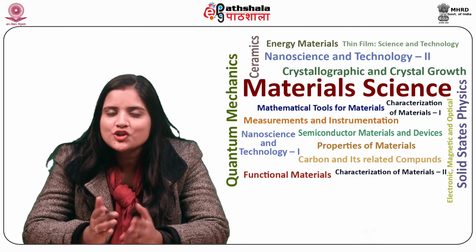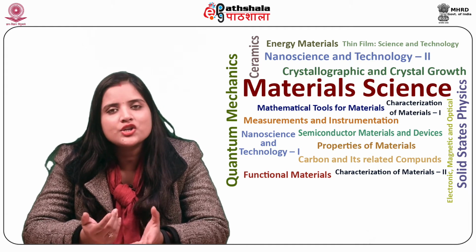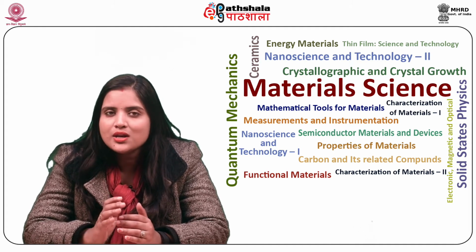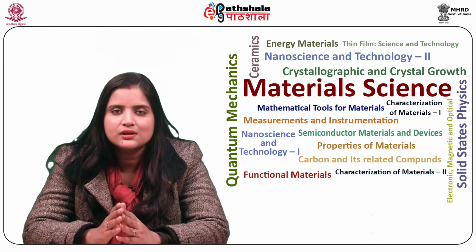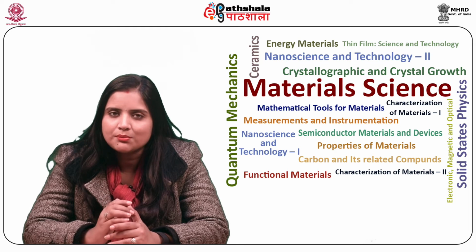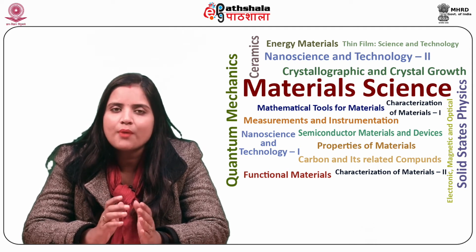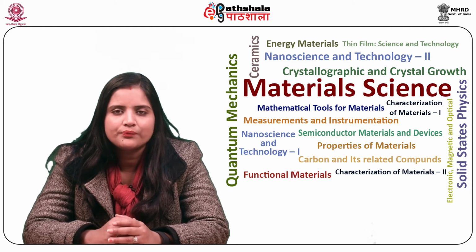The gas phase condensation process utilizes an inert gas at pressures sufficiently high to promote particle formation, but low enough to allow the production of spherical particles. Gas phase condensation employs a vacuum chamber, which includes a heating element, the metal to be converted into nano powder, powder collection apparatus, and vacuum hardware.